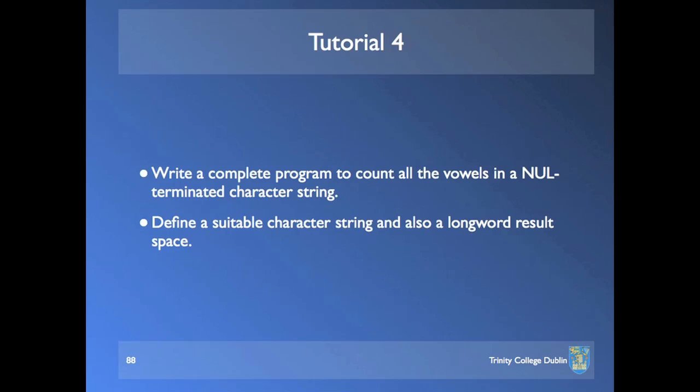Now remember, there's a couple of things to remember here. When you operate on a word, the word part of the register is always the right-hand word, and it has no effect whatever on the upper word or the other word. It's strictly word-oriented. Even if there's a carry or a borrow, it does not propagate up into the upper half at all. It's as if the upper half didn't exist. Any of the bits and any of the values that are in the upper half are not affected whatever by this. So it's just what we want. That's the first thing to remember. And that's the way with all instructions on the 68000, apart from multiplying and dividing.